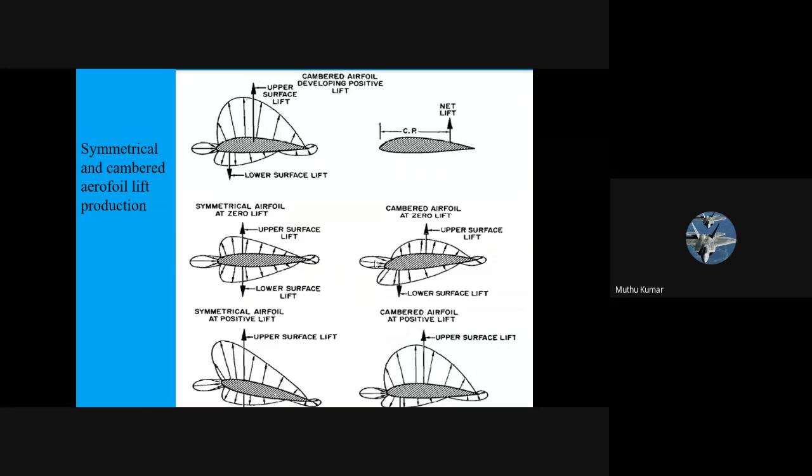So there is a presence of nose down pitching moment in a cambered airfoil. Listen to this. At zero lift. This is the important point here: cambered airfoil at zero lift. I am telling you an in-depth point here. Okay? Even at zero lift, there is a presence of pitching moment in a cambered airfoil.